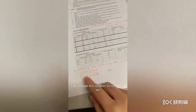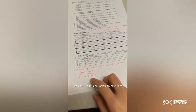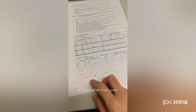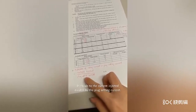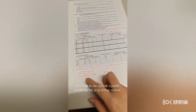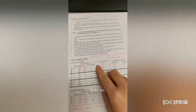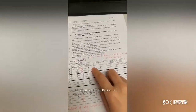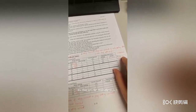So we can use this equation to calculate the multiples of relay current. It equals the current injected divided by the plug setting current. So for this set, the multiple is 2.